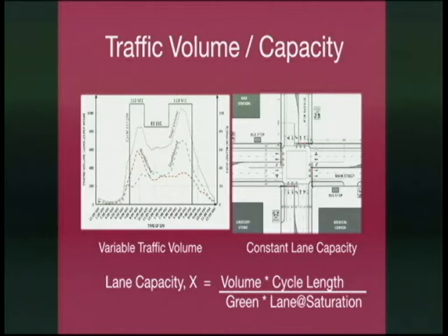There's a value called lane saturation, which on a freeway, if you don't stop the cars, it's about 2,000 cars an hour. When you run the cars through a traffic signal, you're turning the valve on and off. So if you think of it like a pipeline problem, you've got this big pipe with a valve that you're throttling with the traffic signal, and it's how full the pipe is at different times of the day, right? That's how volume and capacity are related at a traffic signal.